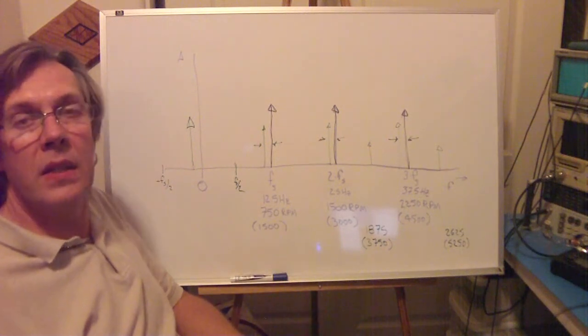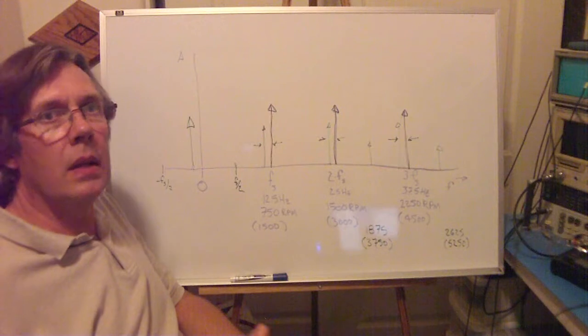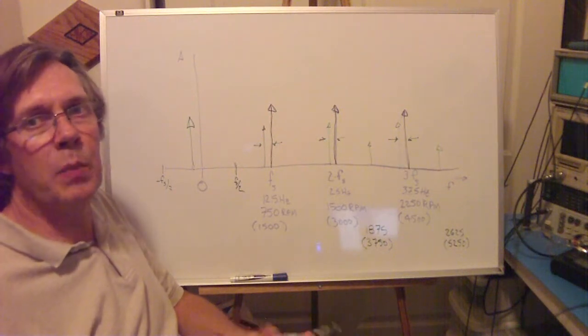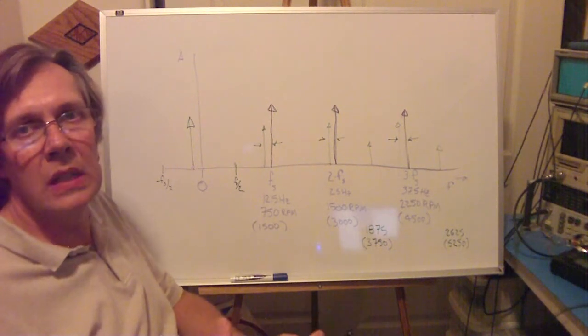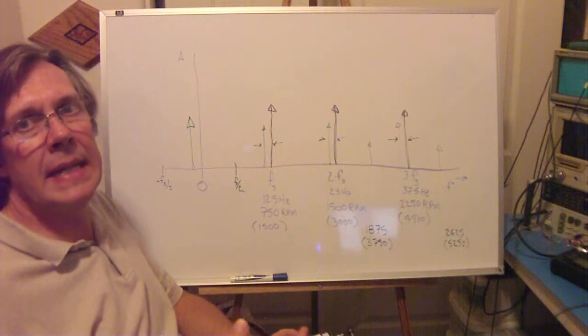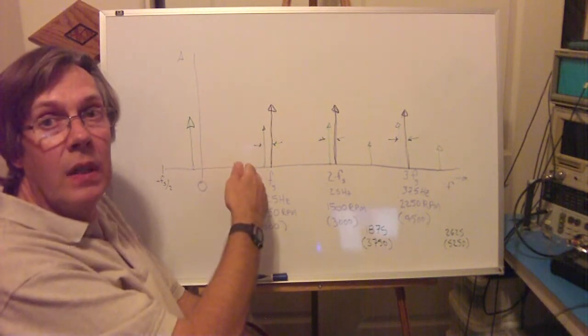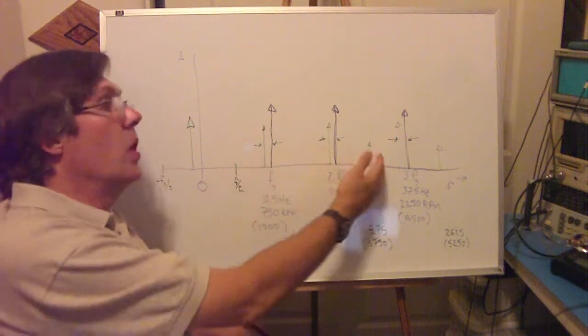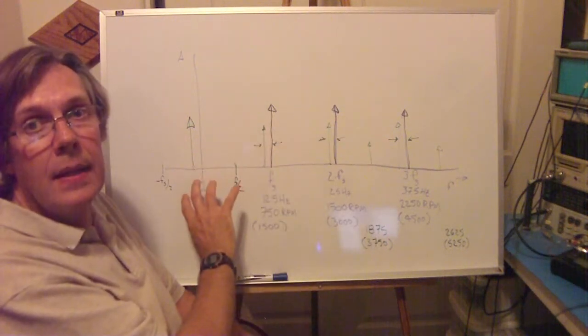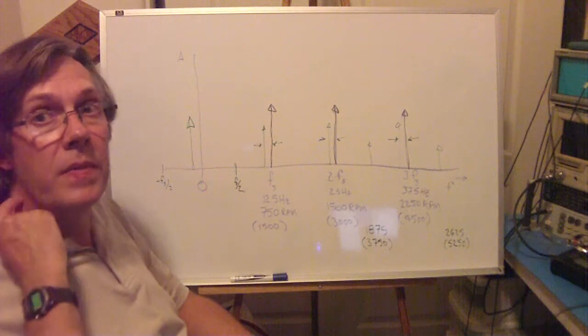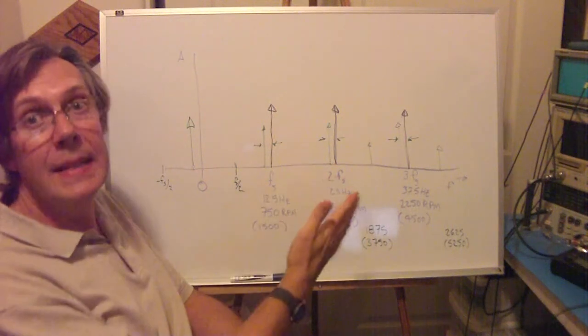And so we have to engineer the system to be that way. In a signal processing system, there can be noise coming in, there can be all kinds of spurious energy, you can have the electronics talking to each other, so you need an anti-alias filter that cuts off all energy above that frequency, so that you know it's not going to fold back in and fool you and trick you into thinking that there's something there that's actually someplace else.